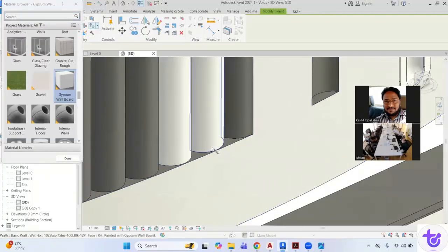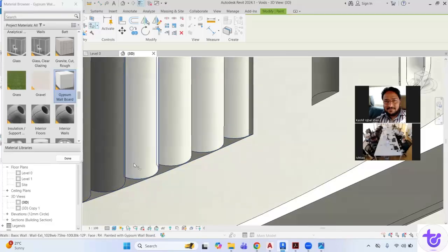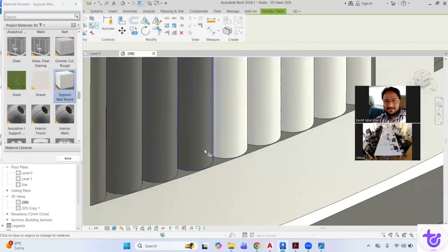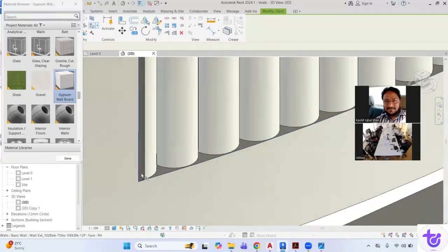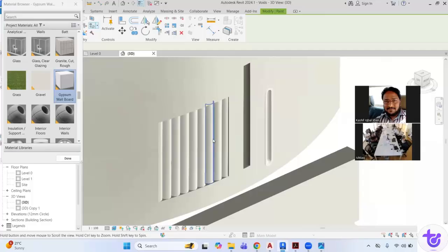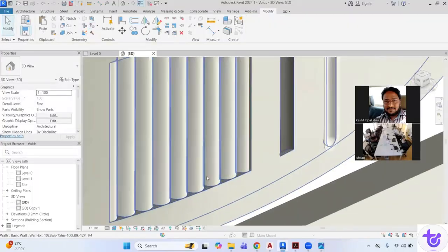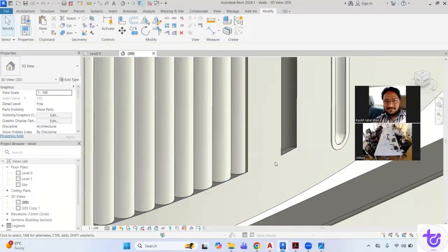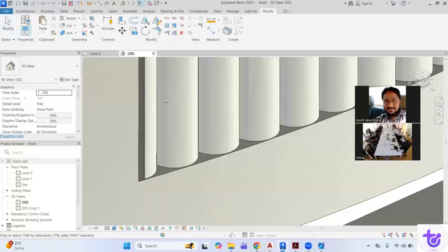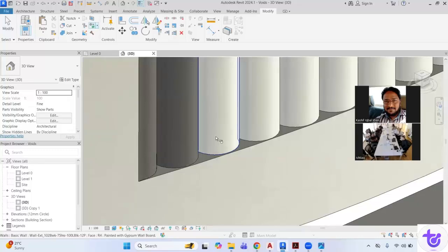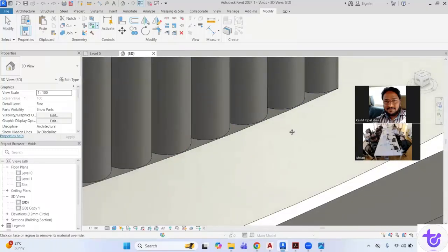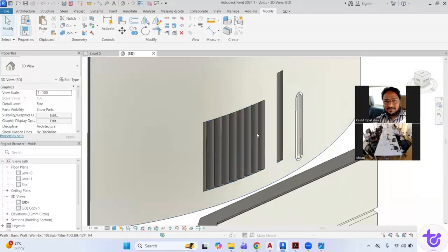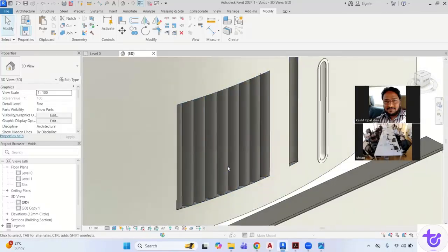Yeah. Because here you'll have to apply the finishes. The graphical representation only there is showing you the plaster, but you have to do it. If you want to have some different finish, you can apply different finishes there. Okay, because if you remove all the paints, it will be the default by category material. There's no material on this because this is a cut portion.